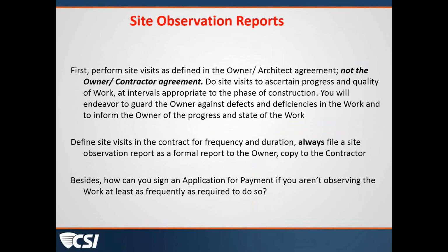I like that. Absolutely. We have talked in the past about pre-installation conferences and the importance of those and how they can be of a big benefit to the project. And just to comment on that, make sure that you've got the right people there at those conferences. In addition to having the contractor, the architect, maybe the supplier, you need to have the subcontract foreman who is actually going to be out on the job at those meetings as well. So he's hearing what the intent is from the architect, and it's not out there assuming it. It just helps to get everybody on the same page.